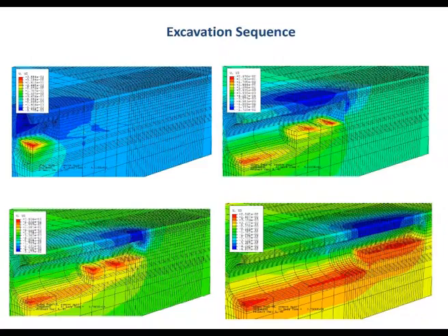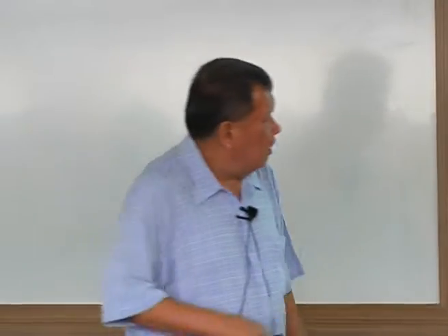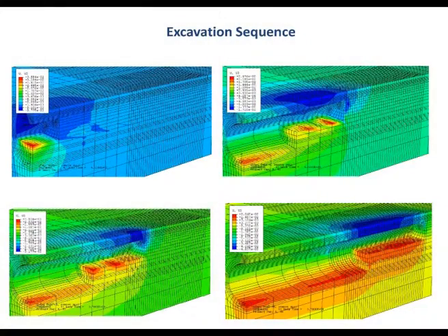I can't remember the number, but it is probably in the region of 150 millimeter to 200 millimeter all round circumferential. Now, there's also shotcrete on the facing. Every time you stop an excavation cycle, you've got to cover the facing. That I think is 50 millimeter or something like that. Okay, 50 to 100. And then the bottom here has to be covered with shotcrete.